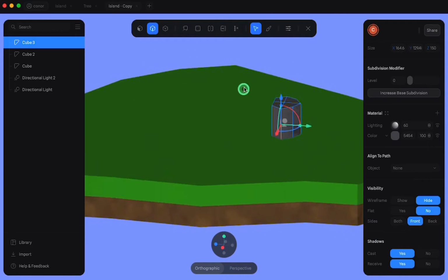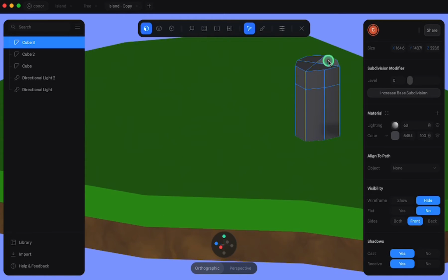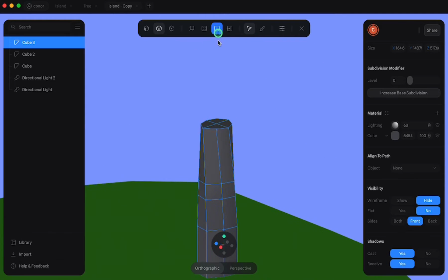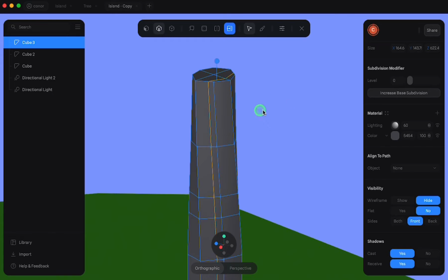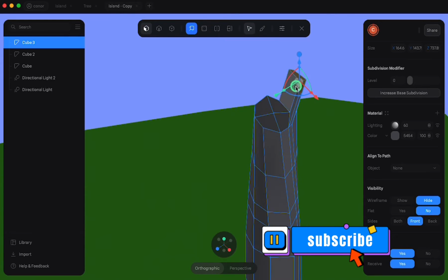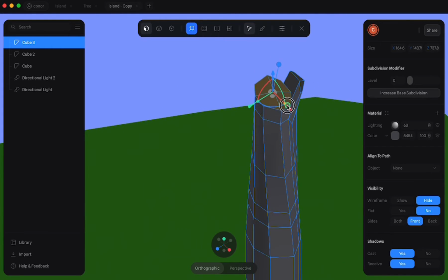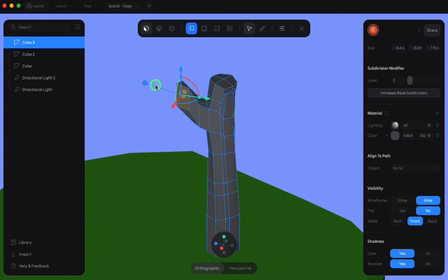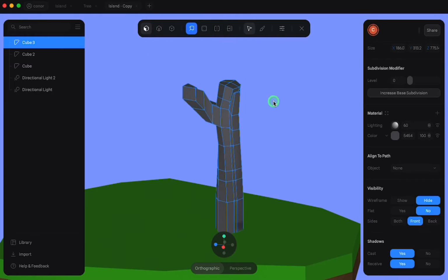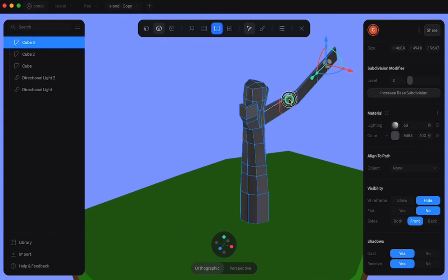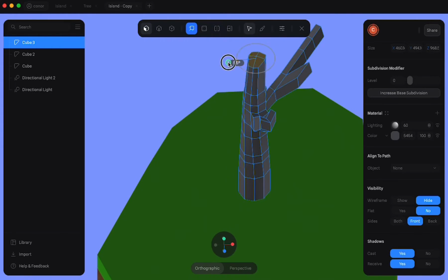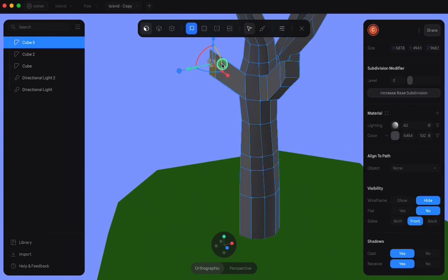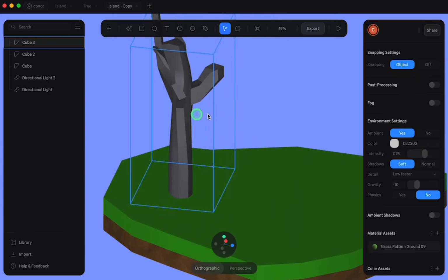Now I'm modeling a basic cube again with a lot of loop cuts to make the trunk of this tree, expanding the faces, selecting individual faces, cutting the loops out to make individual trunks and pulling them out in different directions, resizing and rescaling them and twisting them around to give kind of a more organic look and feel. Once you get deeper into the tree, you can just select individual planes and pull them out one by one in different directions, making them smaller as you go along.